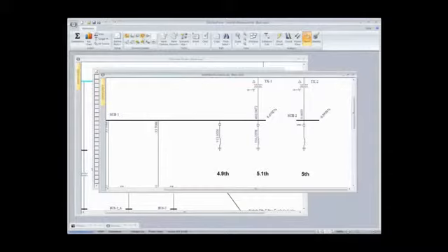I decided, on purpose, to show the root sum square current into each of these filters. Look what it is for one: 220. So if I put this filter online, it really should be 220. They should be drawing about the same amount of current. Maybe they would even be sharing some of the fifth harmonic, so it might even drop a little bit.